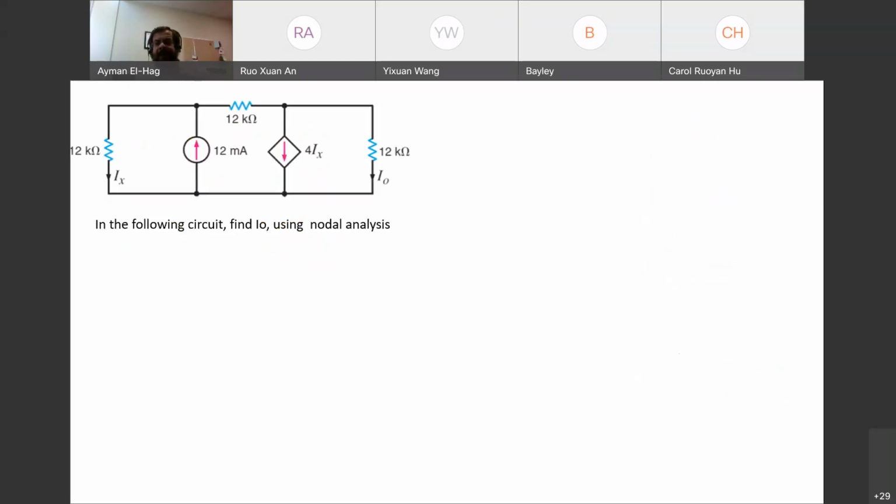Comes to the last one. You will be okay. There's a question here, let me answer it. It says, how do you find the location of the strain gauge with respect to the R's? You will be told that strain gauge 1 is connected as R1, strain gauge 2 is connected as R3. So these things are given to you. The strain gauges will be numbered on the beam, but you will be told which strain gauge corresponds to which R. So you don't need to figure this out by yourself.